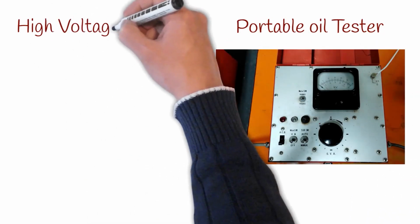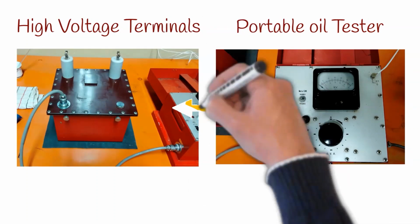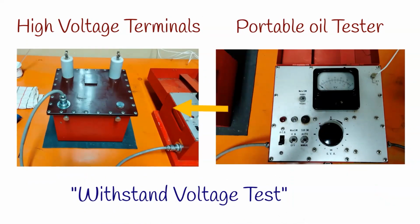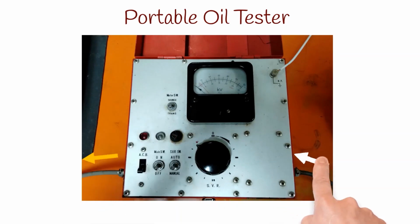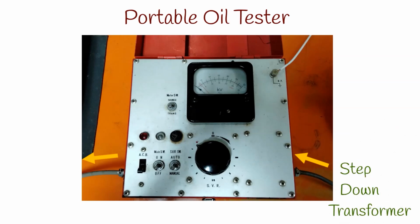Now you can see the portable oil tester with the associated high voltage terminals. This equipment is manufactured for the withstand voltage test of hotline protectors such as insulation oil, rubber gloves, rubber high boots, and oil-contained circuit breakers. So first, take a look at the portable oil tester. As you can observe, there are two connection cords connected to this. Among them, this one is coming from the secondary side of the step-down transformer and the other one is going to the high voltage terminals.